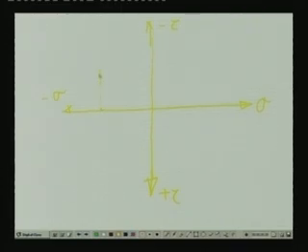So, we get the point somewhere here, which is sigma x as minus 30 and tau as minus 20. Then we have the perpendicular plane, which is y plane, which is 90 degrees with reference to the physical plane. Here in the Mohr's plane that will be 180 degrees, and we have positive sigma y which is 10 MPa, and we have positive tau which is 20 MPa.